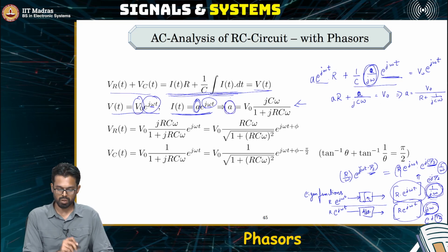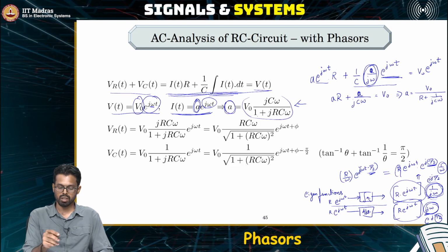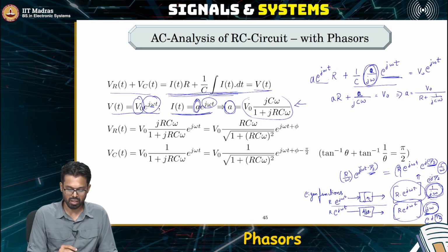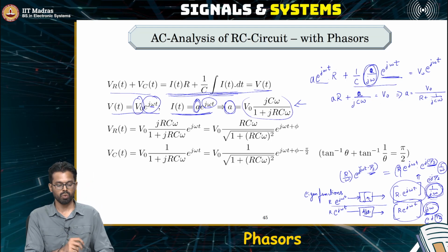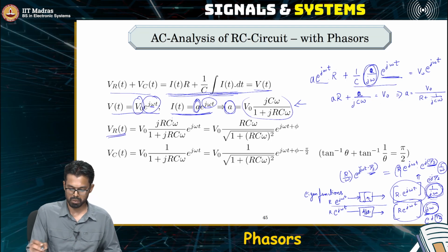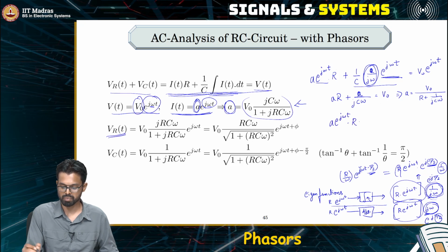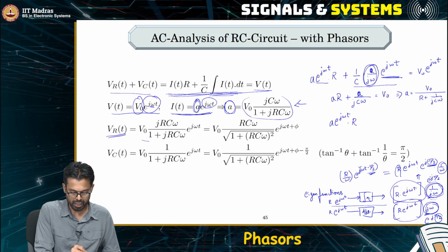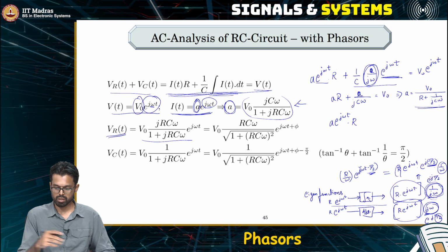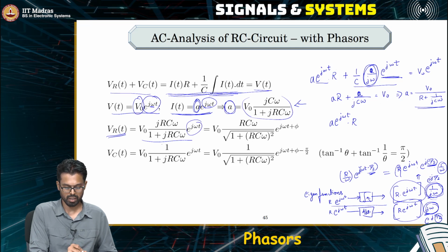Okay, and then we found out the magnitude here. So the magnitude is containing a complex number, of course, which means we have to find out what is the phase that comes out of it. There will be a phase shift. So given that now I of t is of this form, how do we find out the voltage across the resistance? Simply multiply A e power j omega t with R and we are done. We will get this expression. We just multiply this A with e power j omega t that we have here and times R. What we have here is